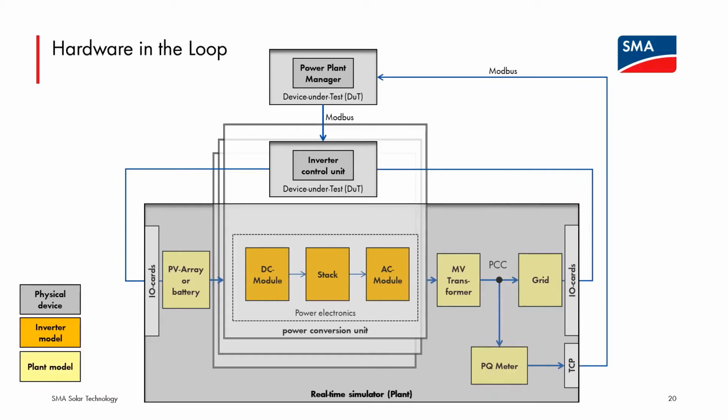So at this stage, the customer does not need the presence of the real physical SMA device, but is interested in having the original behavior as close as it gets, and of course in real time in order to stimulate his protection relays. Normally this would require us to remodel our inverter control system in the native development environment of RSCAD.